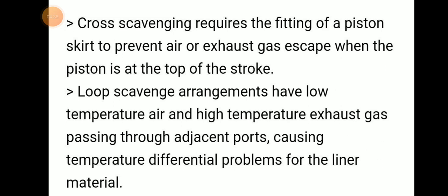But in the case of loop scavenging, there is low temperature air and high temperature exhaust gas through adjacent ports, causing a temperature differential problem for the liner material. The exhaust is placed just above the scavenge inlet, so this causes a temperature differential problem in loop scavenging.